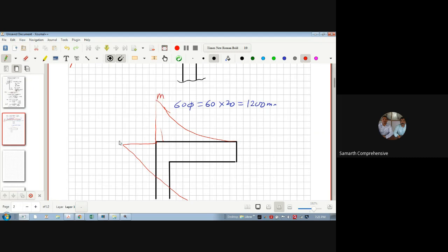So this moment will transfer into this. Whenever I say this moment transfers to this, that means the tension also transfers to that. So I will provide steel here in the cantilever beam at the top. As it is a cantilever, there has to be fixity, and fixity has to be there means there needs to be development length like this.